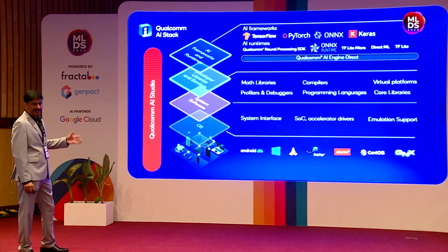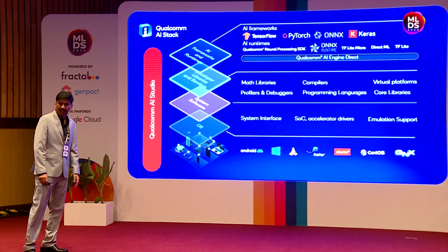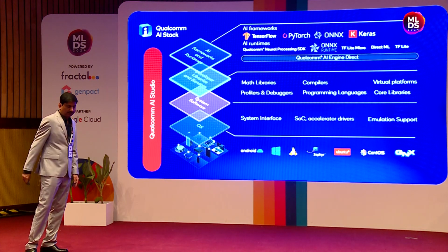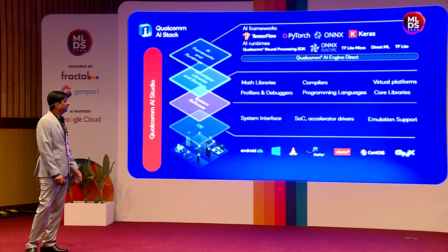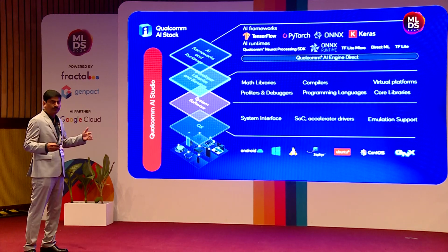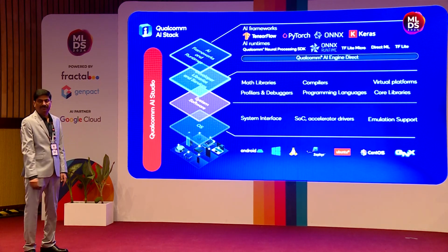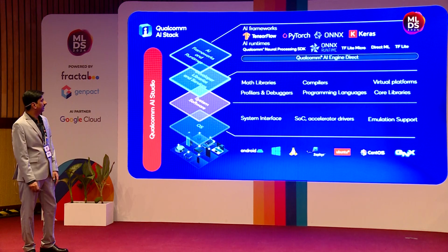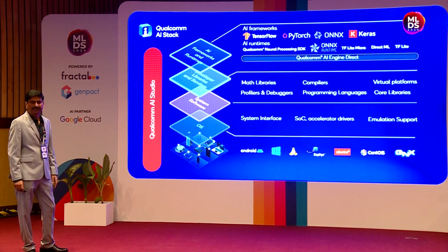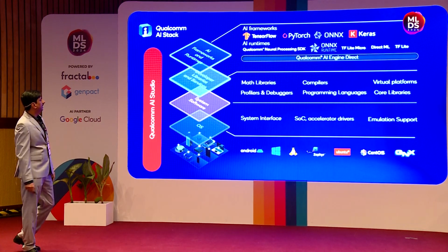You can train your model on whatever your favorite training framework is, like TensorFlow or PyTorch. Then we take that graph and convert, lower it down to an internal IR graph, and do a lot of fusing and graph optimization to make it smaller without losing accuracy. Then we can apply all those quantization techniques, and run it on our chipset with this whole software stack, efficiently on the edge device.